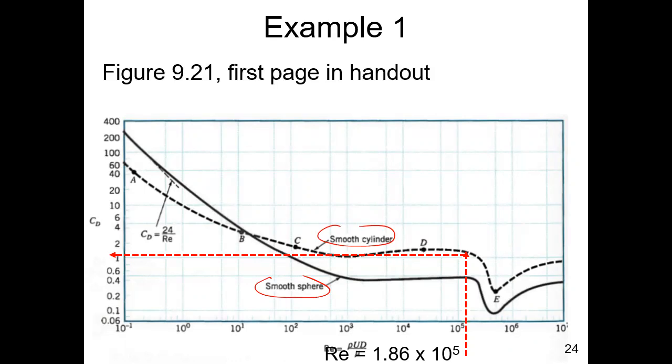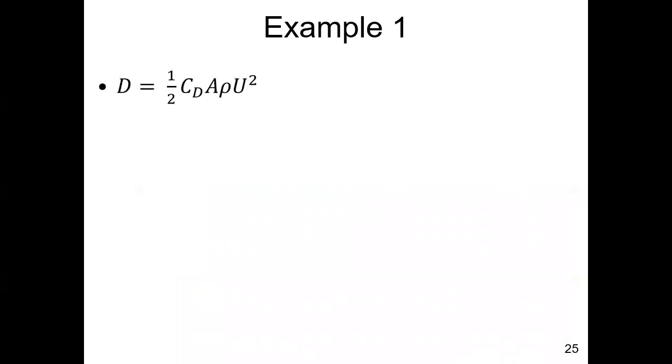So if you take a diagram like this, you should always reference it for your designs, so people know where you got the information from. And it's always good to have another source, so you can check to see if there's a wild difference between the two. When they agree, that's good. When they disagree, now you're going to find a third or a fourth source to figure out which one is the better estimate. So again, we have a drag coefficient of 1.2 for both of these sources.